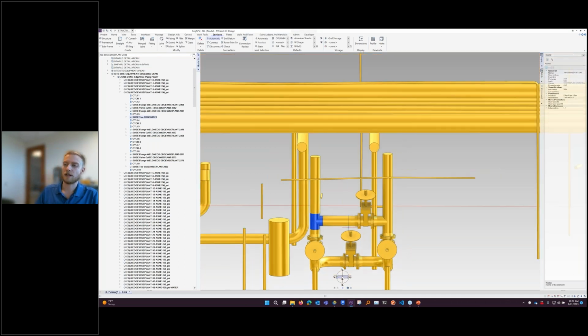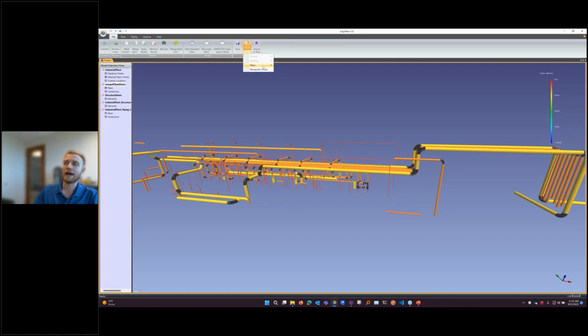is kind of covering this. The last thing, and we don't really have too much of an example for this in E3D right now, but we do have the ability to export point clouds, which we briefly mentioned. So Smart Points is going to export just points near the geometry. So if I want to get more detail for valves and flanges and things like that, I can export that.